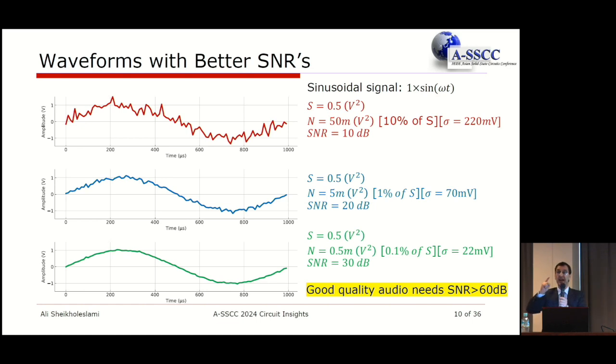So that means a factor of 1 million. So the signal power, your ear is that sensitive. Your signal power should be 1 million times more than the noise power for you to enjoy the voice qualities. Now, this is related to voice and audio, but obviously, depending on what applications, you may need SNR that are much higher than this, or maybe a lower SNR would be okay.